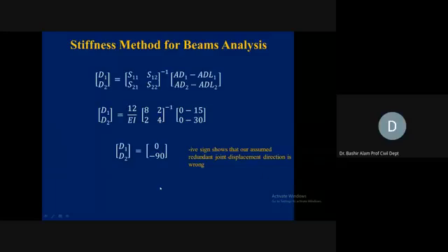Now remember, sometimes the examiner can ask you, looking at the paper complexity and all these things, to just find out and give the rotation at B and C. So your problem is solved. You don't need to go through the rest of the calculations, finding out the member end actions and all these things. You have solved the problem. So you should be careful readers also.